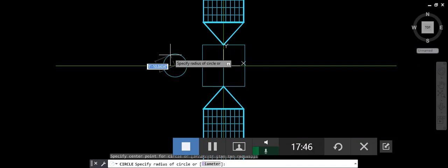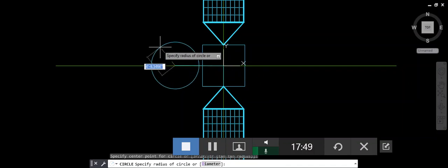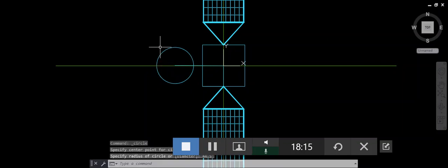You're creating an antenna, but the computer would like to know the radius. Now, when it comes to circles, I don't know why it's asking radius, because in circles the diameters are important, and it's asking us radius, so we're going to give it radius, okay? 89 inches is diameter, that means 44.5 is radius, so 44.5 inches, and inch mark, enter. Okay, good.